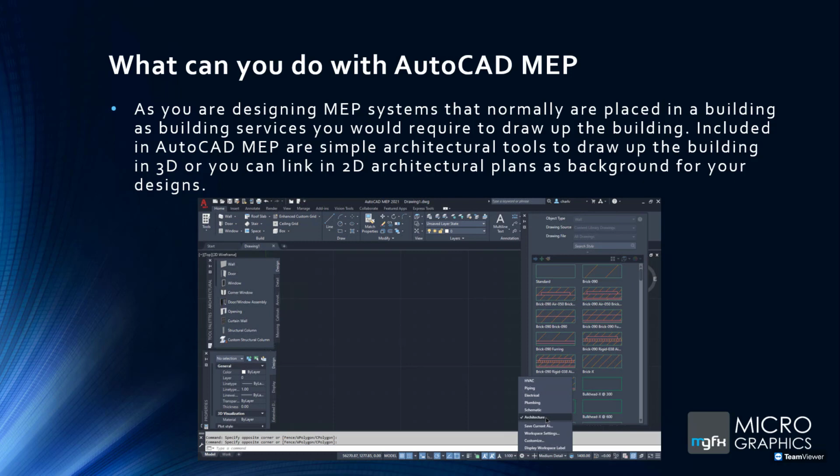Right, in saying that, yes, you can have them in 3D, or you can simply import or open the 2D plans. Although those 2D plans don't have heights, you would use them as a background reference, and then just draw your ducts, pipes, and electrical information at a height, over this 2D plan. Obviously, we're looking at this from the top, so you won't see the heights of the walls.